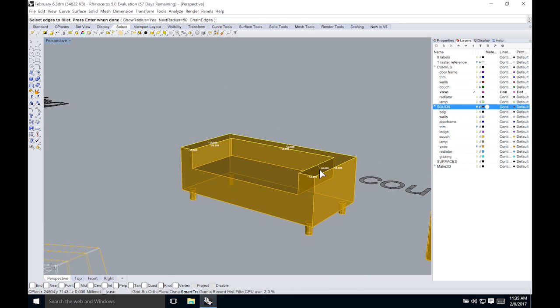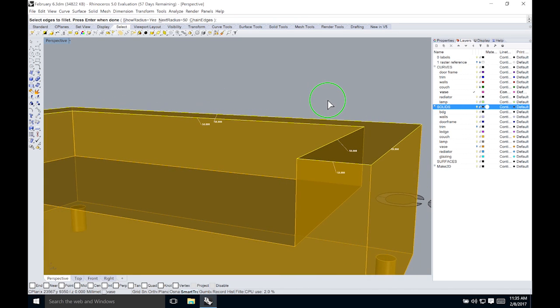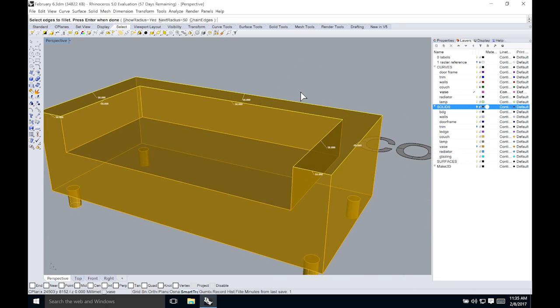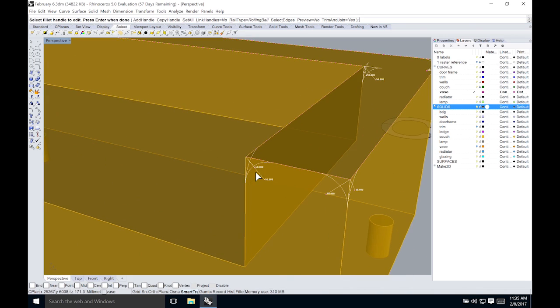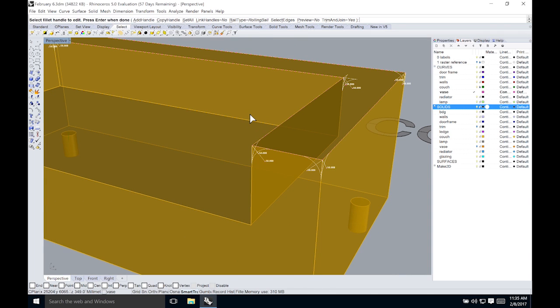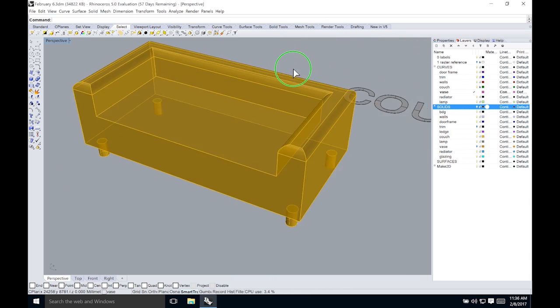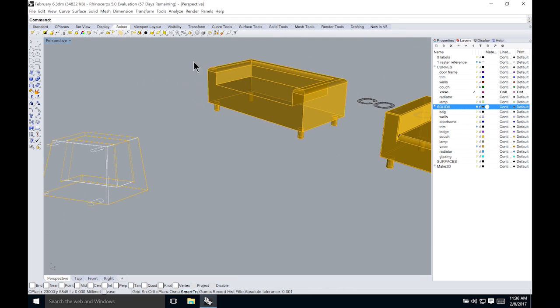So you can see that now they are outlined, or each of them has a little number 50 next to them, and then again click on chain edges, and so I didn't want to adjust those options, so just keep pressing enter until it's cycling through all of them. And so now you can see that it's actually giving me a preview of what's happening. And so if I think that looks good, then I can finish it.